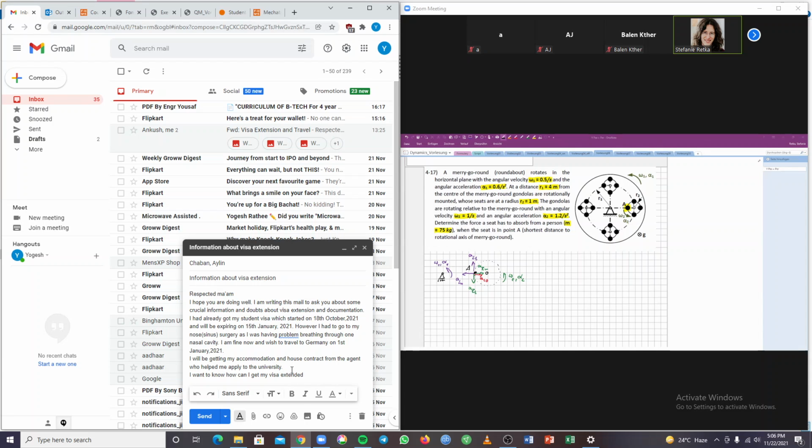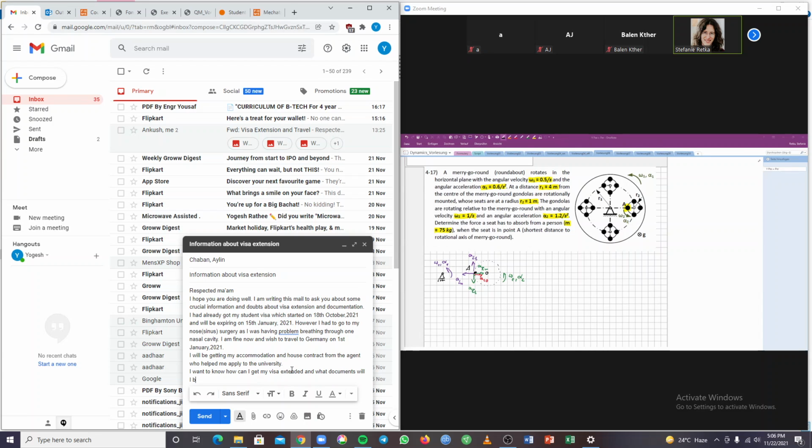It's a rotation, which means we have to consider the normal and tangential components of the acceleration. The relative motion is also a circular motion with omega 2 and alpha 2, and the normal and tangential components of the acceleration accordingly. And then, since our leading motion is a circular motion, we have to consider Coriolis acceleration. So we have to find the correct direction of Coriolis acceleration, which is the one depicted in my graphic here.